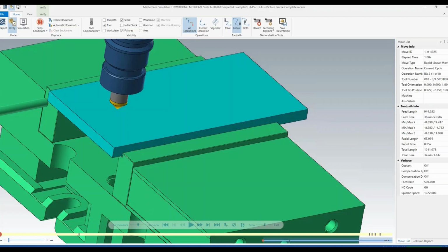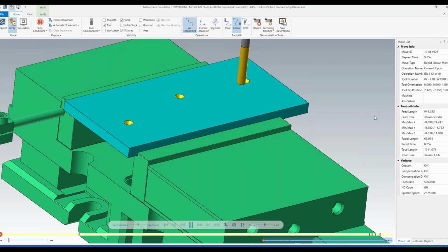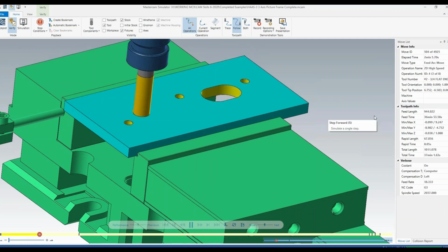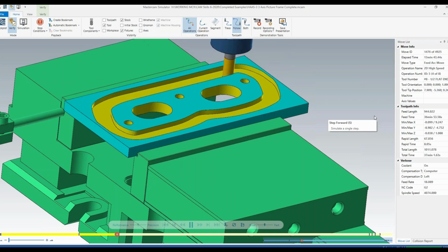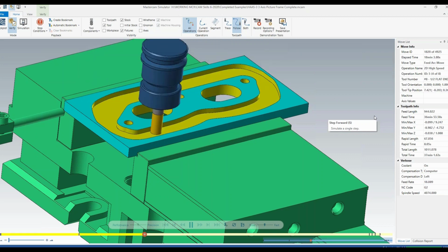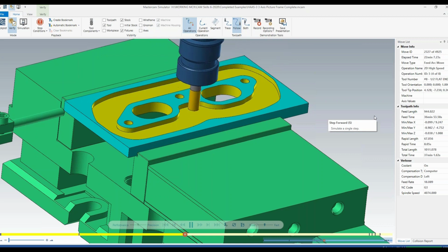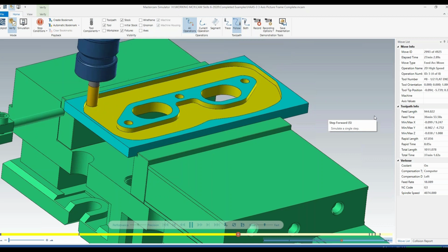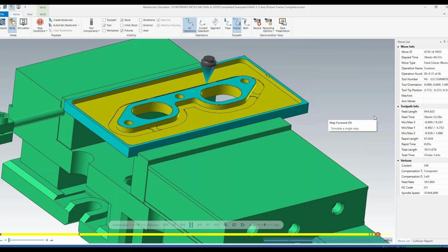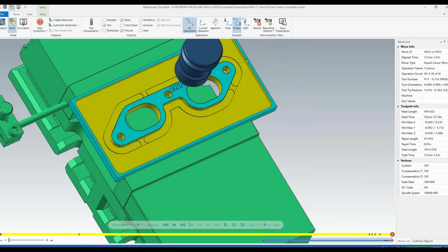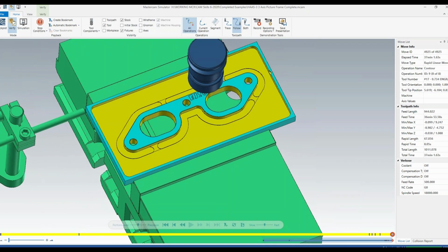Stock models are by far the best way to transfer what I'm doing on one side to the other side. So this is everything I'm doing on side 1. You can see I'm just basically relieving some material from the part around the periphery of it, doing the holes, doing the things. A little exaggerated with that. I'm just roughing out the basic picture frame and a little bit of engraving and putting in a couple of tab points, right? Now, the important thing I want to make sure I'm doing is that I want all of this to transfer over for the second operation, right?